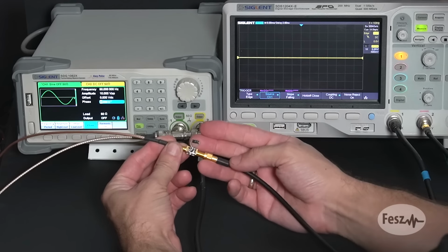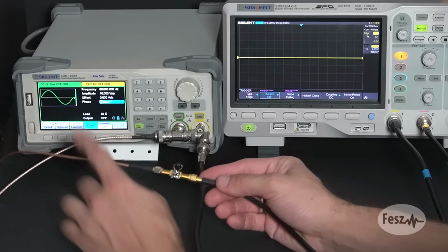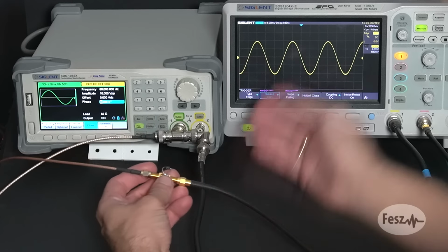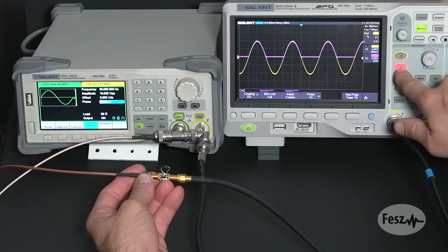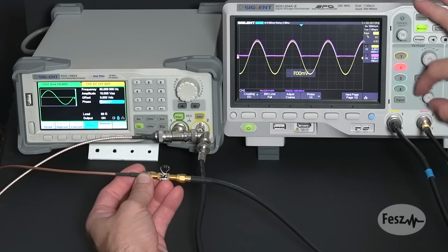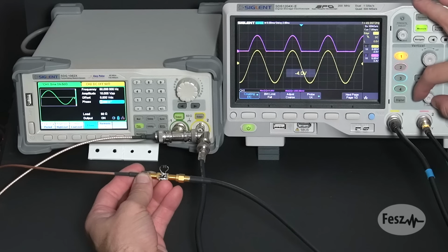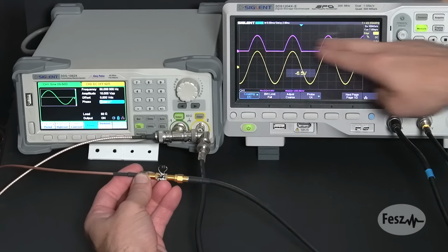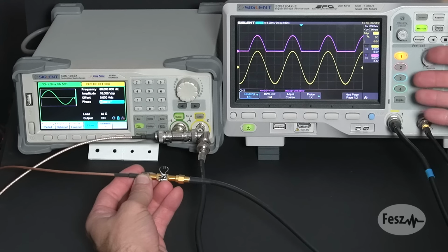Now, the fundamental purpose of a diode is to let current pass through one way, but not the other. This is easiest to illustrate when a sine wave is applied to one side and only half of the waveform passes through. Even though it's not that obvious, the component is working like a switch. If a direct current is applied, it turns on and lets the current pass, and if the current is trying to go the other way, then the diode turns off and blocks the current.